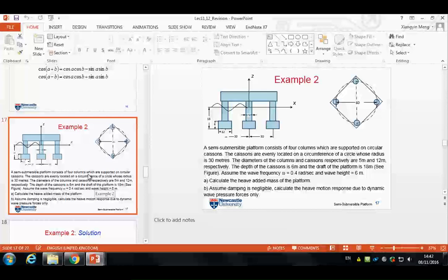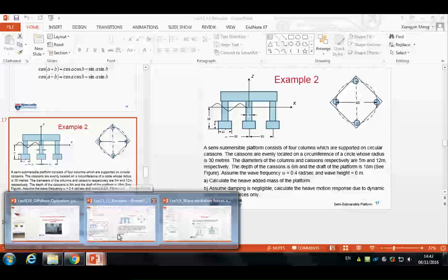Sorry, regarding the forcing, when we calculate this wave excitation force, for example, for a submerged object like that one. So in this example, we were asking about heave force, but the same is there. We have a formula for the excitation force, which is heave force and the surge force, not added together. So in this situation, what kind of wave excitation force is it?